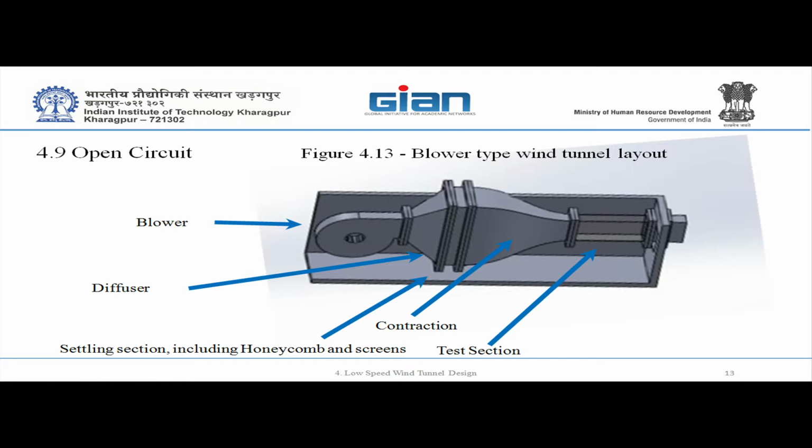The faster the velocity is, the higher the losses are, because as in pipes or any other flowing element, the head loss is proportional to velocity squared. You remember this?